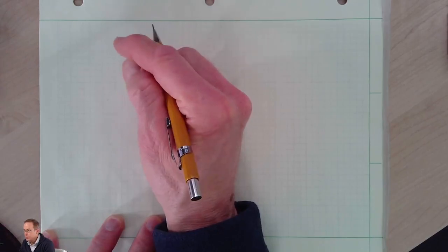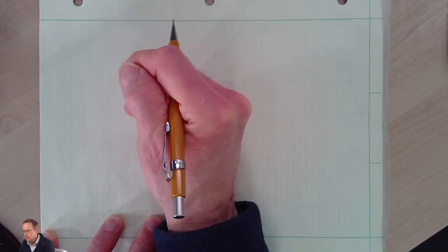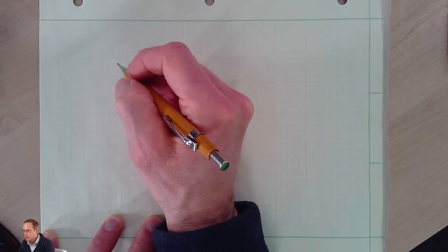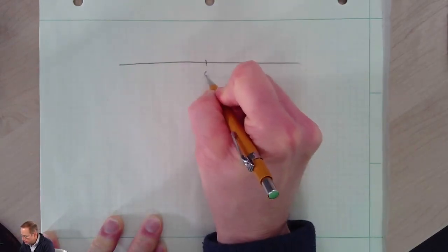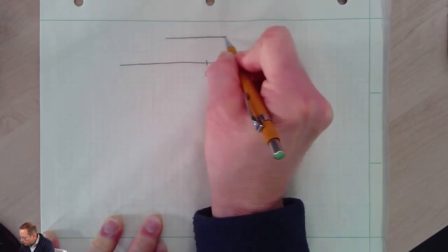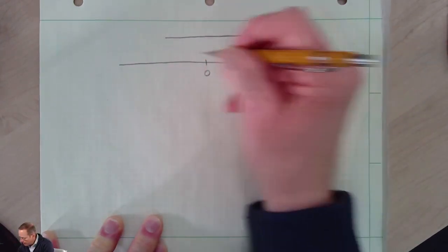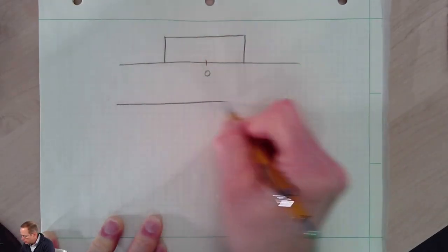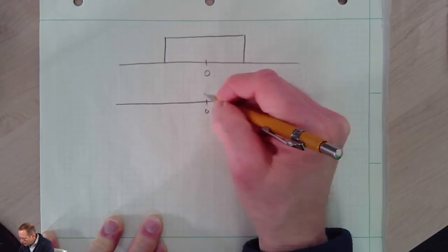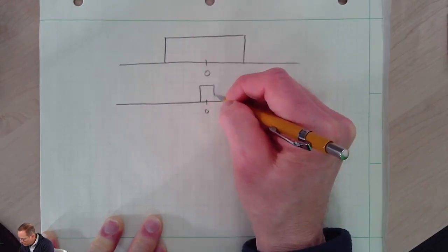And if in the time domain we're multiplying two signals together, what we're doing in the frequency domain is convolving two signals. So what I want to do is just illustrate this convolution. So the Fourier transform of the first sinc function is a wide rectangle, and the Fourier transform of the second sinc function is a narrow rectangle.